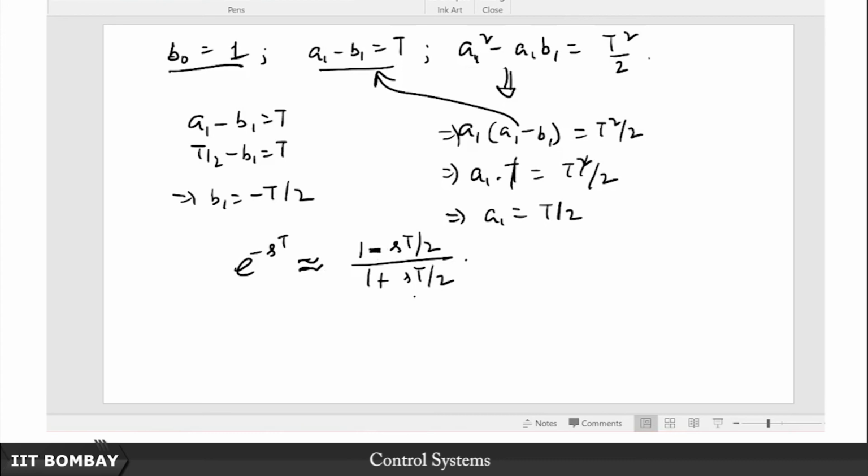So a time delay term is always approximated by a rational non-minimum phase transfer function. One way of obtaining these non-minimum phase transfer functions is if the physical model itself governs it, like a canard controlled aircraft. The other way is if you have some semblance of a time delay which can reasonably be then approximated by a rational transfer function, it will always involve such right half plane zeros in the open loop.